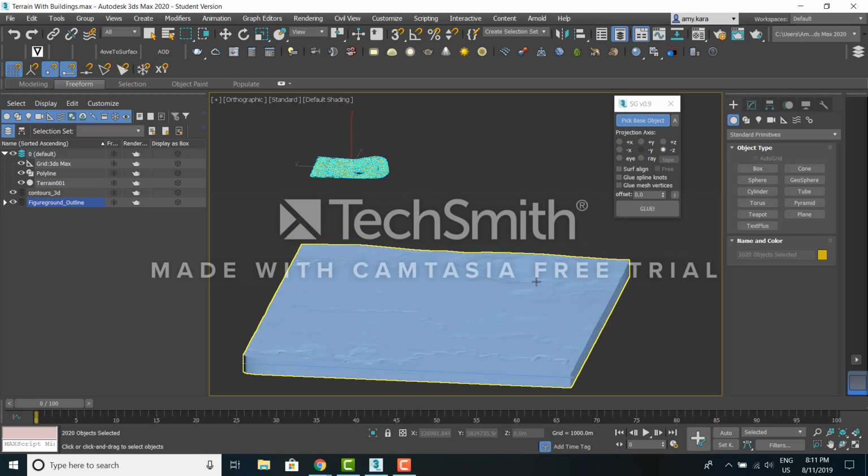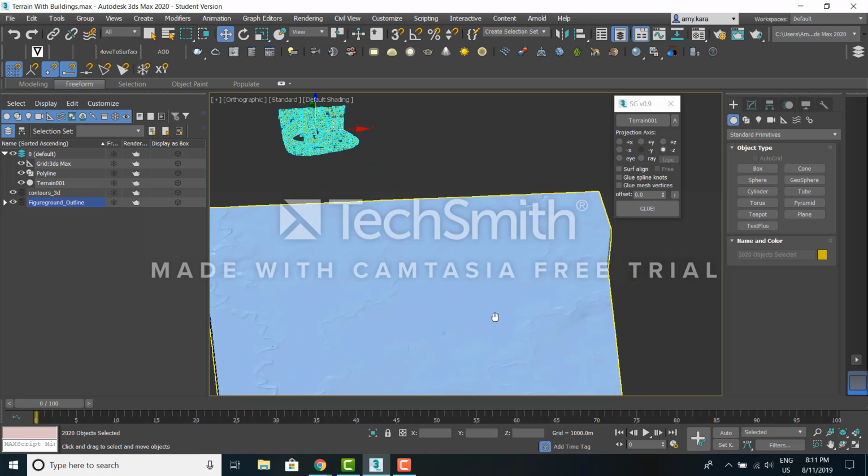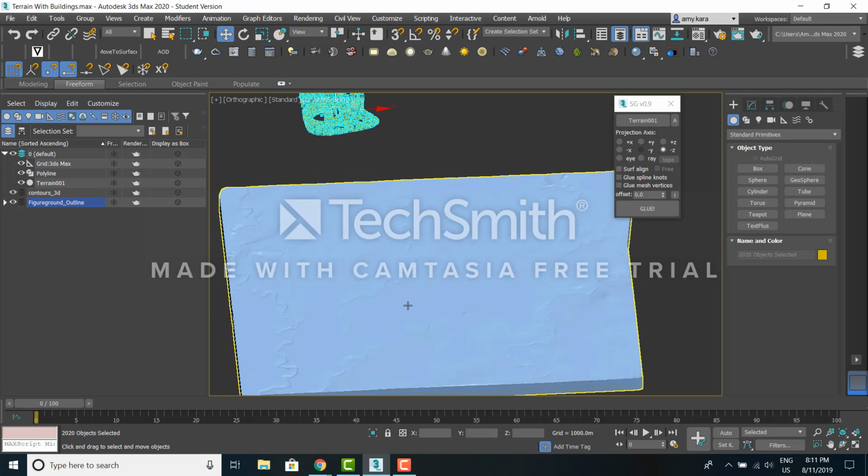So we're going to select the terrain, and then we're going to choose the Z axis on the underside of the buildings, as this is the axis we want the buildings to sit on the terrain. And then we are going to give it an offset of just below the terrain in order to make sure that these buildings glue together.